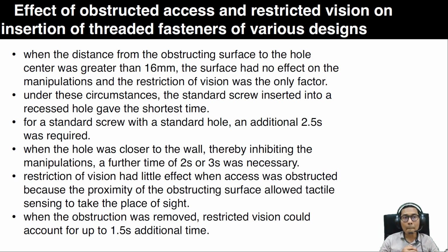So what are the effects of obstructed access and restricted vision on insertion of threaded fasteners of various designs? When the distance from the obstructing surface to the hole center was greater than 16 millimeters, the surface had no effect on the manipulations and the restriction of vision was the only factor.